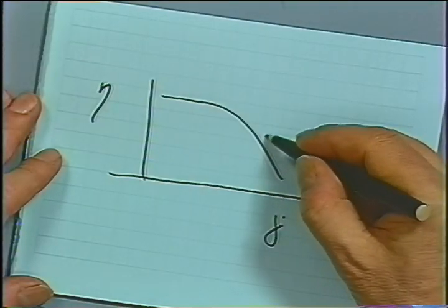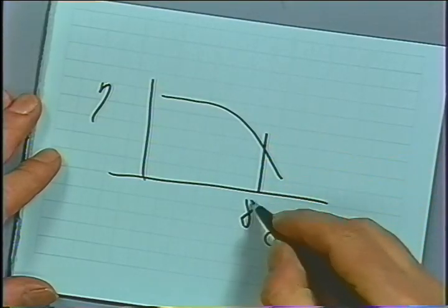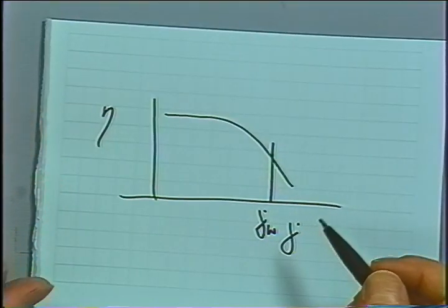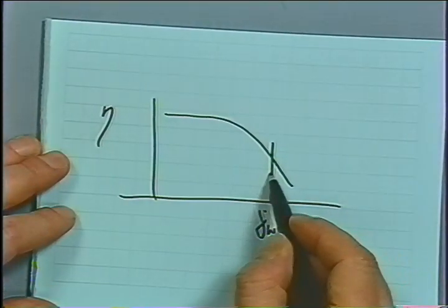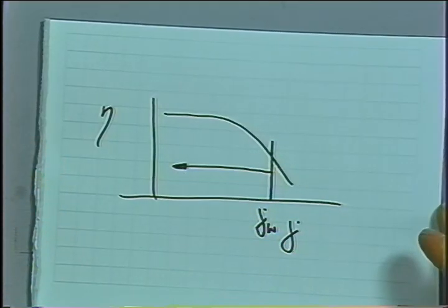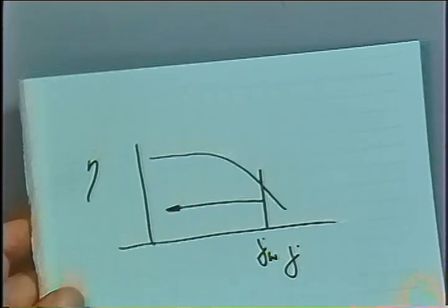Now, the highest shear rate occurs at the wall, if this would be gamma dot at the wall. And 0 shear rate occurs in the center of the capillary. So all those shear rates are probed in the capillary when we extrude the material through that die. So from that viscosity function, we really take a whole range to describe the flow.